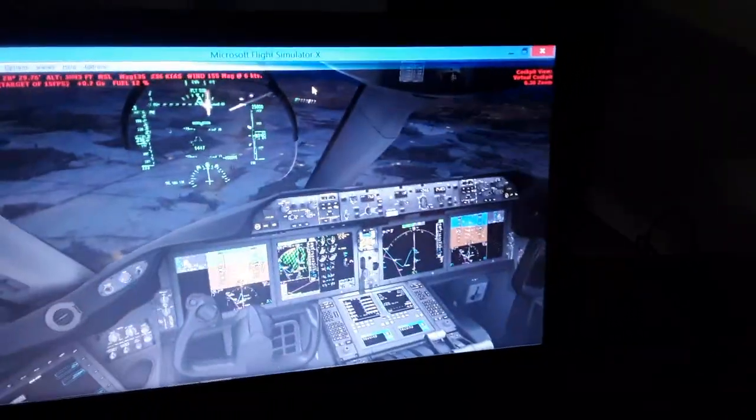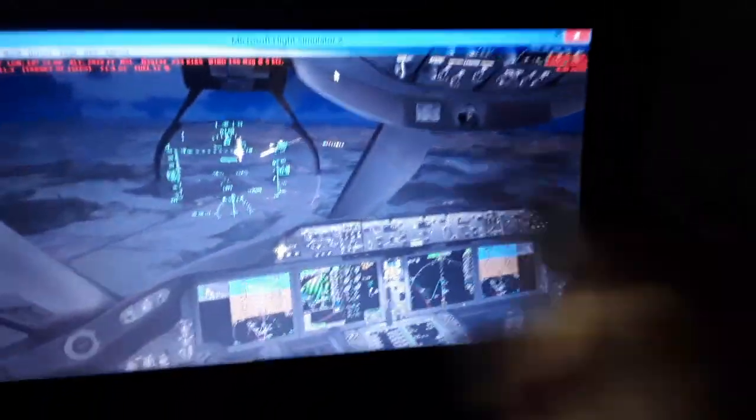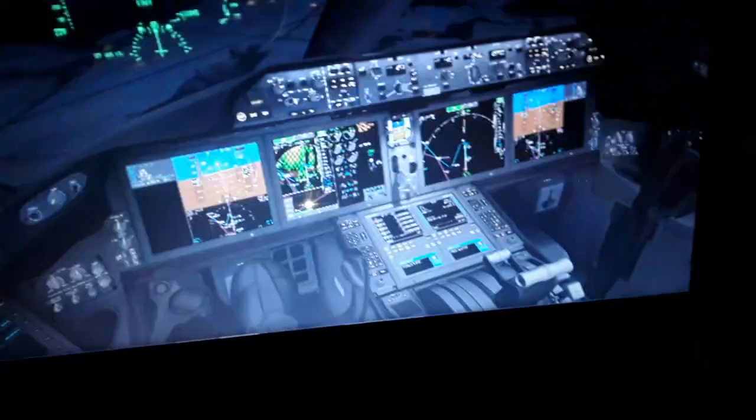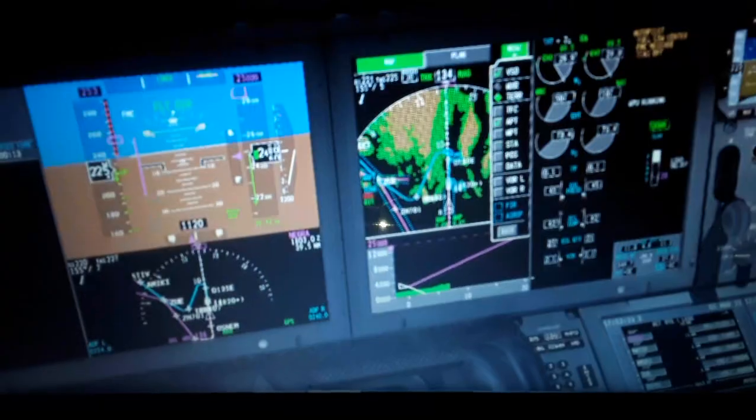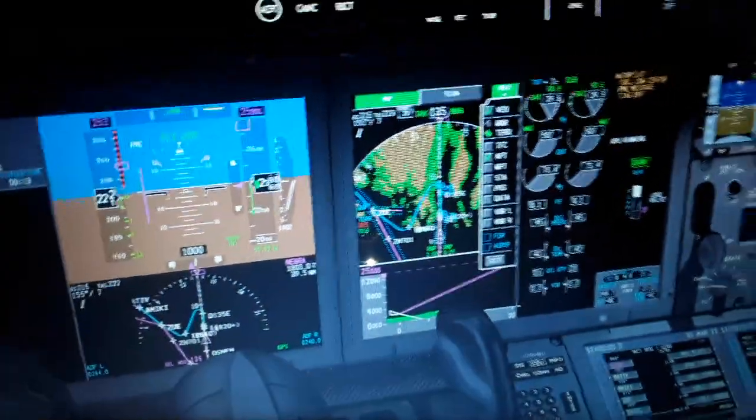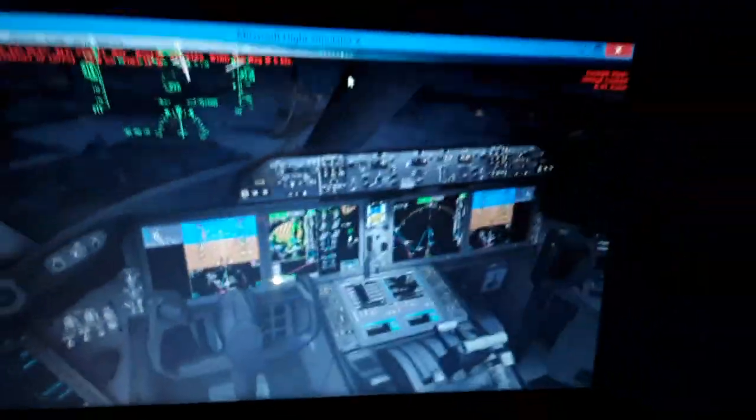So we have 1 more minute for approach and landing. We can see the runway. We have also the LSZH localizer here. You can see the localizer we need for alignment. We need to follow the localizer approach.